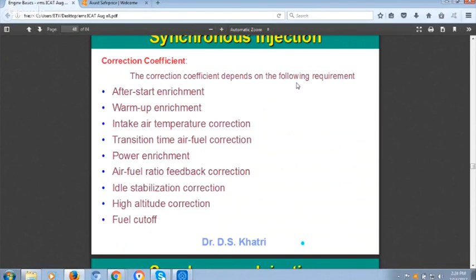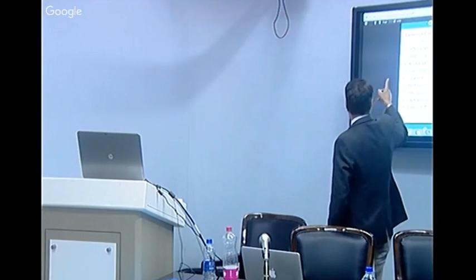when we are cranking. Earlier you were providing a choke to start the engine in the early morning or in the winter. Now there is no choke in the EFI system. What the choke means is that it is making the mixture rich. So there is an enrichment circuit, an enrichment strategy. The first thing, what I am writing, is start enrichment.